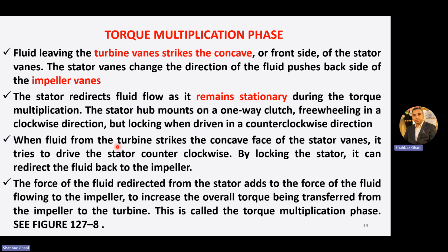When the fluid flowing from the turbine strikes the concave face of the stator vane, it tries to drive the stator counterclockwise. By locking the stator, it can redirect the fluid back to the impeller.